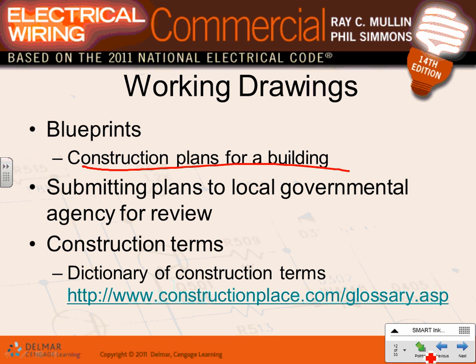Why do we need all this documentation? This becomes part of your legally binding project. Also you have to submit it to the local government agencies for approval. If you build a hospital, you're going to submit it to the city council for approval, right? So blueprints and specification, especially blueprints, will be used for getting approval from the cities, as well as from utilities. If you want power, they ask you to have a riser. Give me the riser or the major equipment that you're going to have, the electrical utilities, so they can see if they have enough juice to feed you.